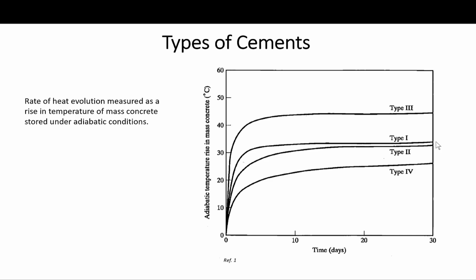Okay, so also, one thing to remember, the hydration reactions of Portland cement are all exothermic. That is, they liberate heat. So during the hardening process, the concrete is being continually warmed by the internal heat generated due to this action. The extent of the temperature rise in a concrete section will depend on how quickly the heat is liberated and how quickly it is lost from the concrete to the surroundings.